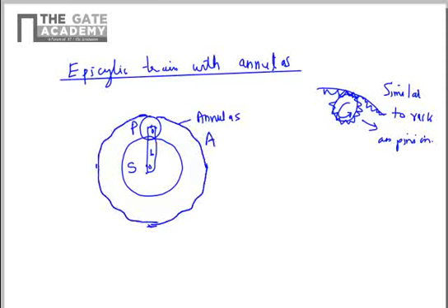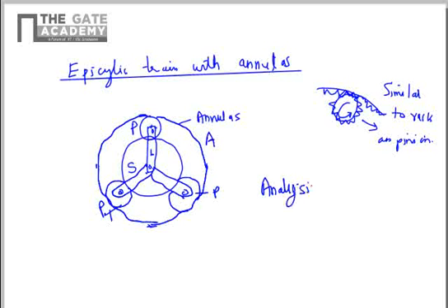In some cases, you will see a three-legged epicyclic train, but basically it's the same structure. In that case, you have this 1, 2, 3 web. This leg is called the web now, and you have three planet gears, P. This is also P. But if you do the analysis for single-legged or triple-legged, the velocity ratio comes to be the same.